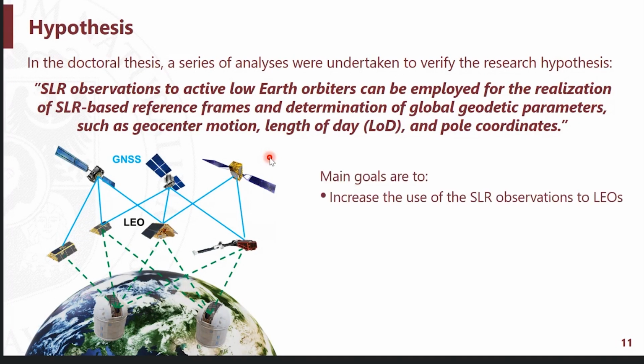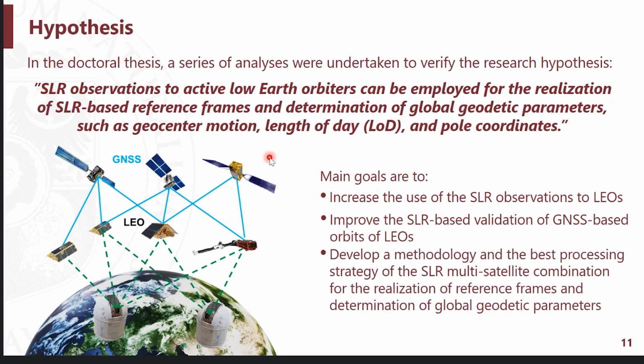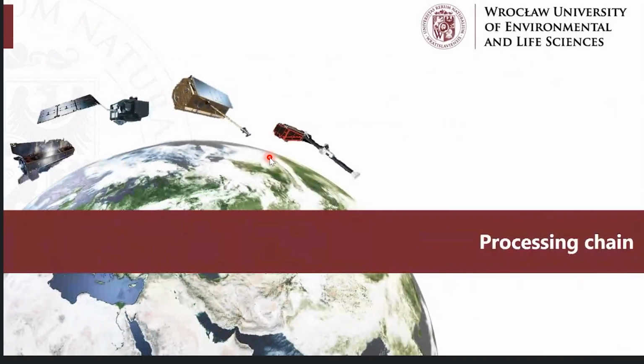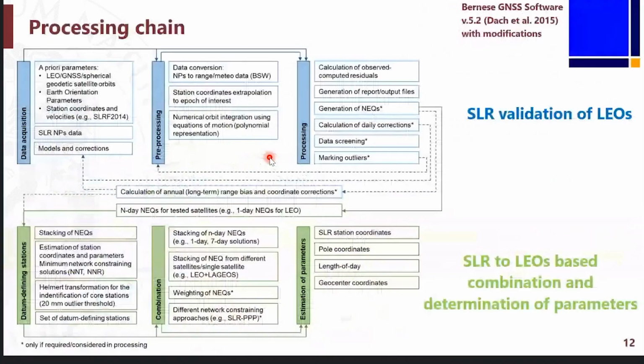Main goals are to increase the use of SLR observations to LEO satellites, improve the SLR-based validation of POD products, and develop a methodology and best processing strategy for multi-satellite combination, aiming at determination of global geodetic parameters and reference frame realization.